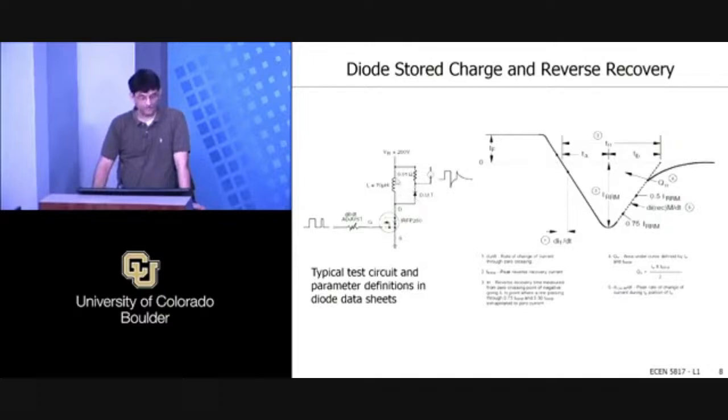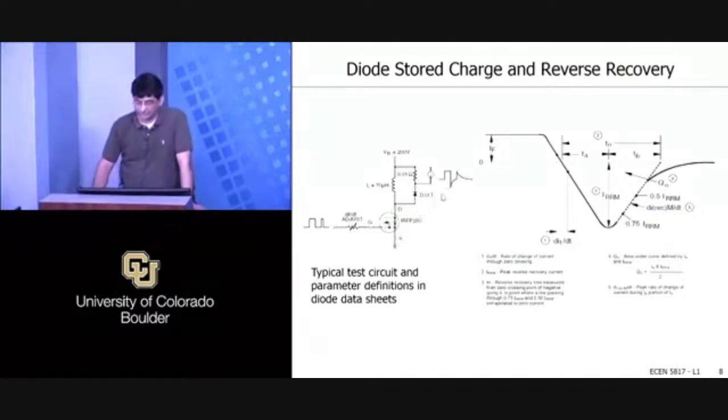And there is the inductor. So the inductor current is going through this diode, and at the same time you're going to turn on this device, and so you're going to see that reverse recovery through this diode. Essentially it's the same circuit, just things are kind of backwards. The diode is above and the MOSFET is below, but nothing else is different.